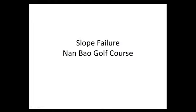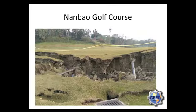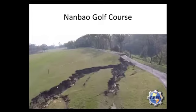The failure at the Nanbao site is a failure of a golf course. There's no liquefaction involved, other than it is a failure along a cut fill slope. The important thing is that this will be a case history for us to calibrate the Newmark sliding block analysis. You see, it's almost moving like a rigid block, so it's a good calibration for Newmark sliding block analysis. I want to talk about dam performances.